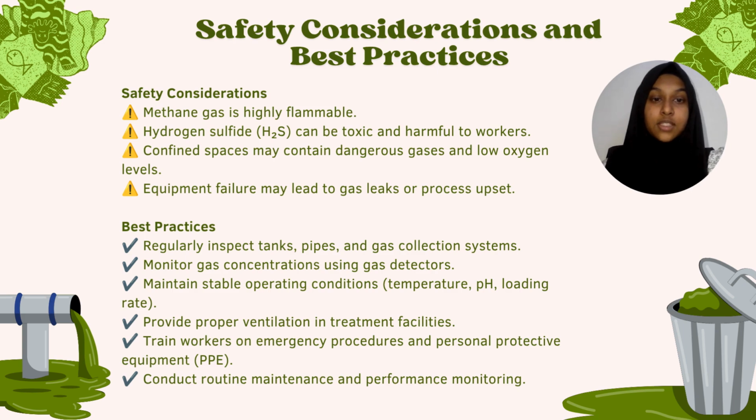We have best practices too. Regularly inspect tanks, pipes, and gas collection systems. Monitor gas concentrations using gas detectors. Maintain stable operating conditions like temperature, pH, and loading rate. Provide proper ventilation in treatment facilities. Train workers on emergency procedures and personal protective equipment (PPE). And last but not least, conduct routine maintenance and performance monitoring.